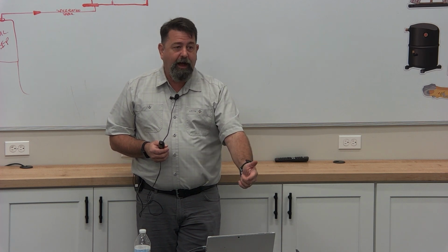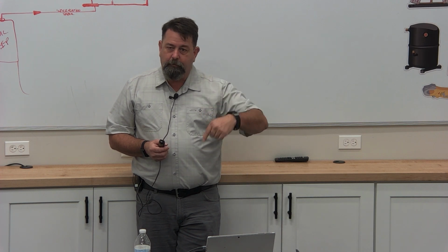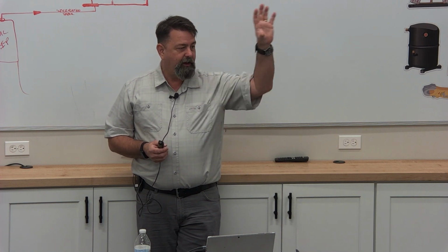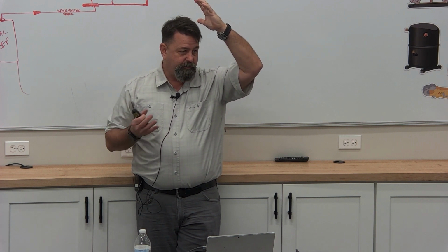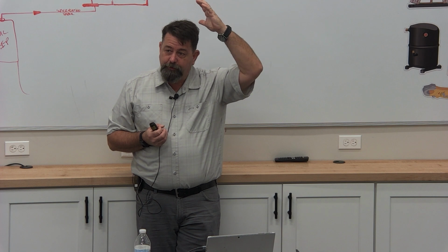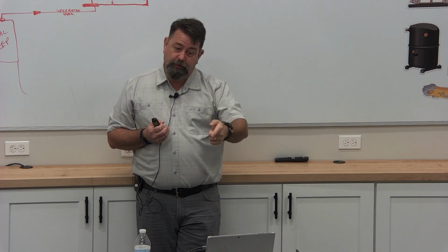I'm gonna engineer this case, and of course I'm not, right? Someone is gonna engineer this case, and they're going to expect some air to spill out of this case onto the sales floor. Well, just like an air conditioner, if I'm blowing a duct into the attic, right? That return is gonna suck that air in from somewhere, right? Well, that's what's gonna happen here.